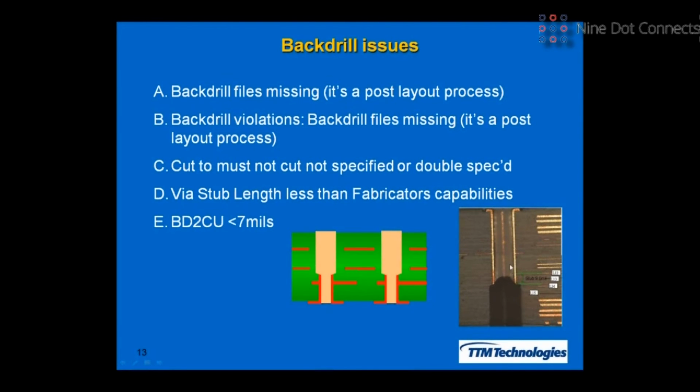Electrically, you don't have a bunch of energy being robbed going out beyond the actual interconnect. The interconnect may come in and shoot across the layer, and then you have this given stub length. The length of that stub is typically determined by two things: the electrical requirements set by the OEM, and the fab shop's capabilities. Some shops may be able to do better than others. It all depends on where you're sourcing and procuring these parts.